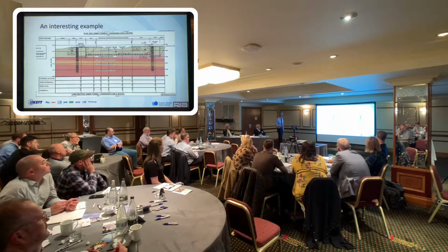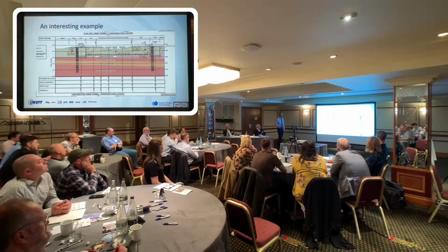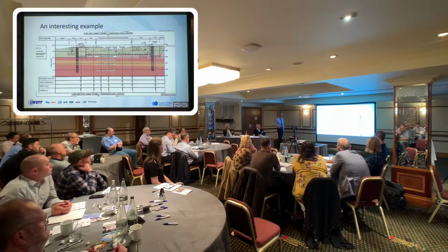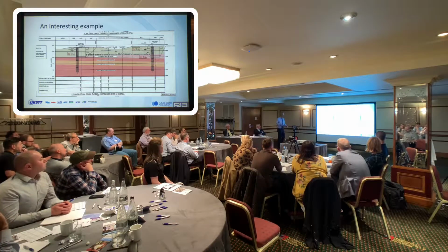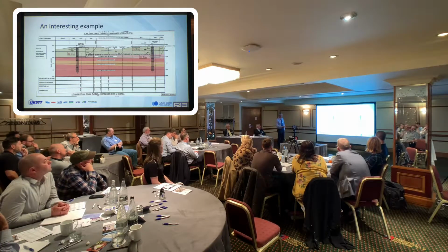So a number of options were considered. One option which was considered was a contiguous or secant pile shaft where we sink piles, but that involves a very big rig coring through very hard material next to a railway, and then you've got the collapse radius of the rig onto the railway, which is another problem to deal with.